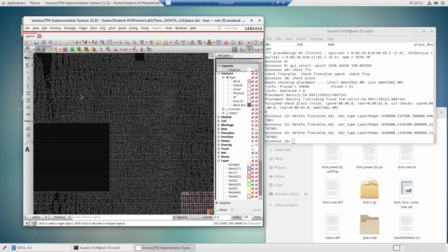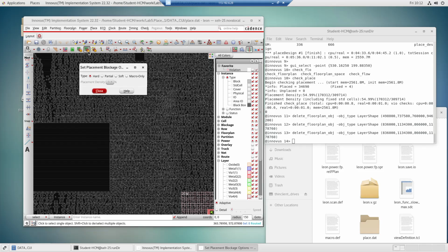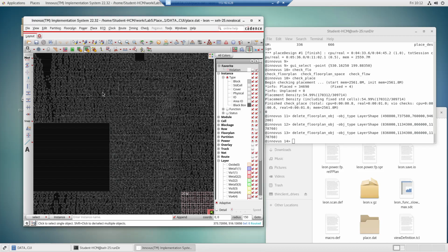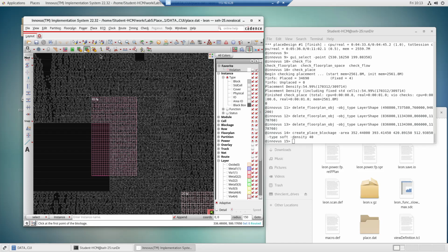Yeah, I think what Ting might be referring to is that if you have a very high speed block, say a DSP block, and you know the hierarchical name of it, you can set some target density on that block. So you don't have to physically draw it, but you can apply it to a functional block. Per module based density. Yes, yep.